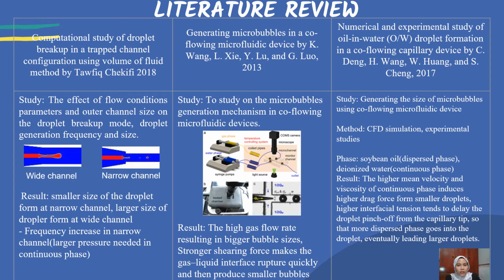From the result, the small size of the droplet is produced by the narrow channel, and the larger size of the droplet is formed by the wide channel. The frequency increased in the narrow channel because the pressure of the continuous phase stream in the confinement region is bigger compared to the larger model, which leads to easily and quickly pinching off the thread of oil to form the droplet. The second literature review is generating microbubbles in a co-flowing microfluidic device.